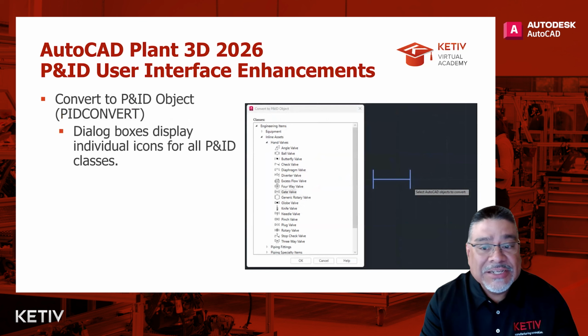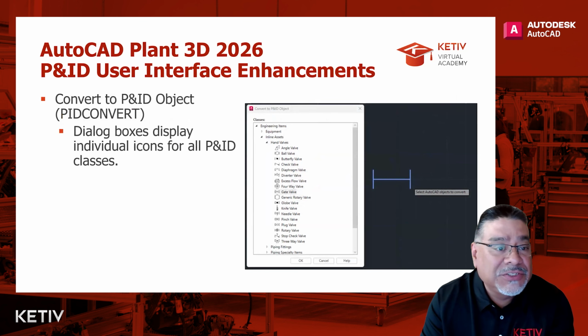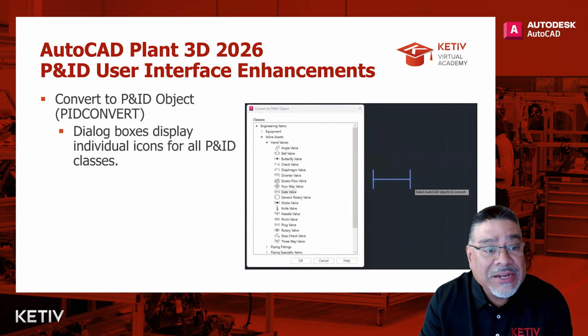So the next thing we have here is convert to P&ID object. So your P&ID convert command that you would typically use. Here you'll see the dialog box when you're going to the convert command, and then you're actually able to see the individual items that you want to convert it to. So a big change here as well. That way you have more of an idea of what you're selecting when you're doing that conversion from an AutoCAD object to a smart P&ID object.